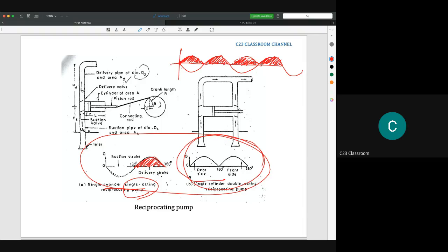So it means that in this situation, the water in the extra tank called the air vessel will top up the flow rate. So it will top up here, and then we have an extra volume here, and so on and so forth. So finally we could see that the flow rate is almost constant. That's why in this graph the y-axis is Q, the flow rate. I think you could imagine the mechanism of the air vessel in a piston pump.